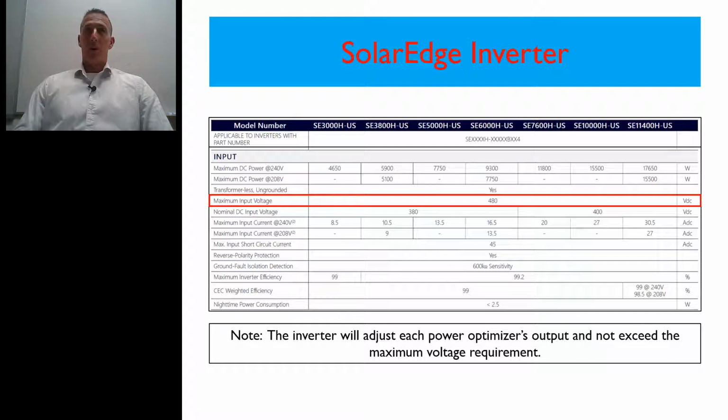So I would feel safe connecting up to 50 of those converters in series on a 480 volt system with a 480 volt inverter, and not exceeding the rating of any of that equipment we're connecting to. You're going to balance that with whatever converter and whatever inverter you're using, and you want to make sure you match all of those up and meet the minimum and maximum string lengths.